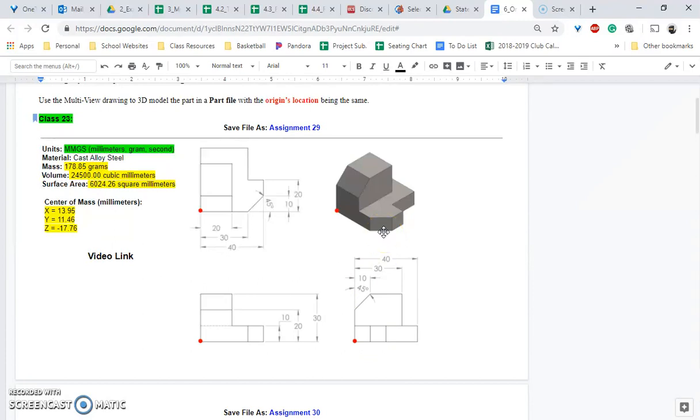So what view is the best view? Well, maybe the top view. Well, if I draw from the top view, I can get rid of it here, but once again, I'm still adding material. So maybe there is not a lesser of the evils. In this case, I think it's easiest just to draw this thing from the top view because you can extrude the whole entire bottom piece up, then you can extrude this whole entire thing up, and then you don't necessarily have to make another sketch to cut this off. Since this is slanted, we could just use the chamfer feature.